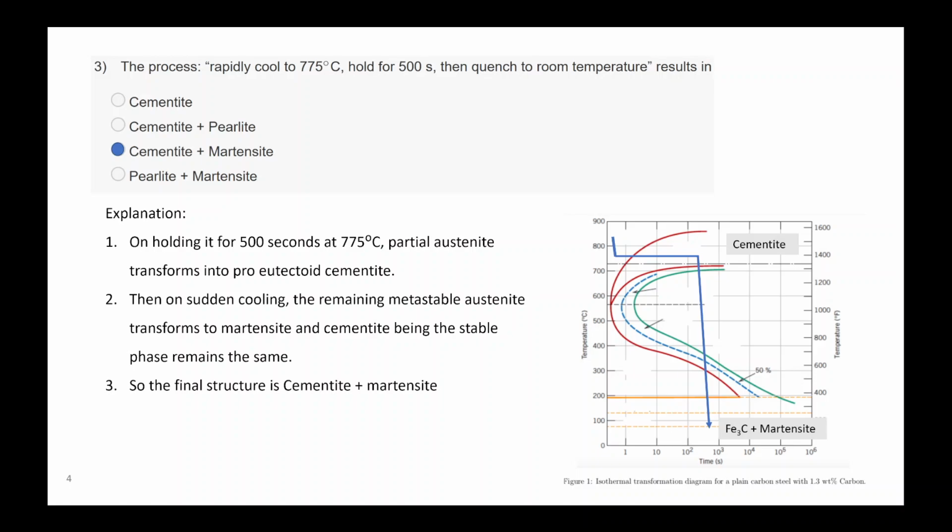Ma'am, you're saying that in a real case, experimentally it will be low. The impact strength will be inversely proportional to the yield strength, and graphically we will get a real graph. The graph that you get by using a very low strain rate, when you apply uniaxial tensile testing, gives a toughness that is different from your impact toughness.